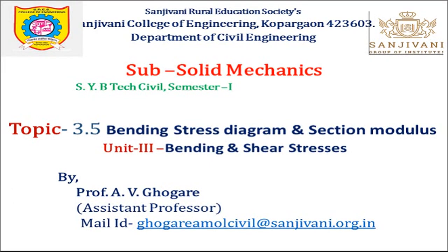In this session, we are going to study the topic bending stress diagram and section modulus. These are the two important terms we have to study in this video lecture. In the earlier video lecture, we went through the flexural formula. We know the flexural formula: M divided by I is equal to sigma by y is equal to E upon R. You should remember that formula because it is important for solving further problems on bending stresses.